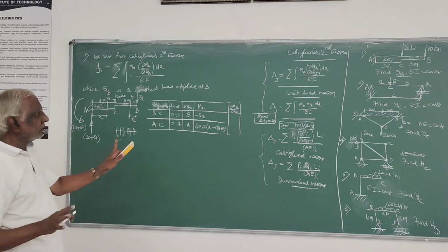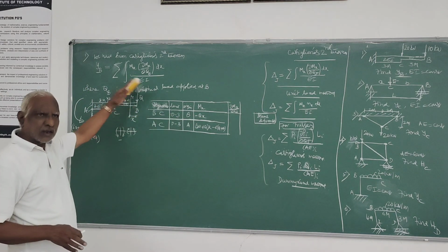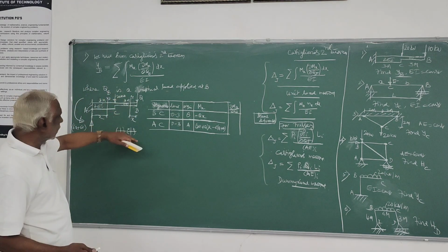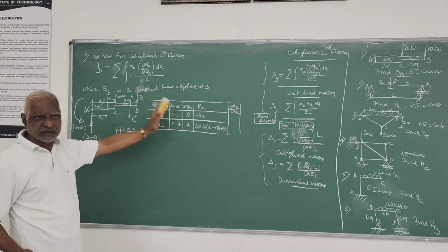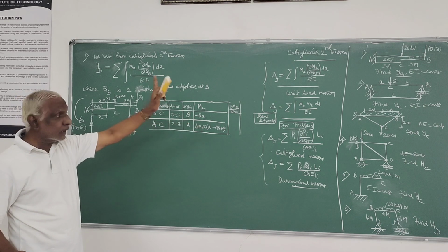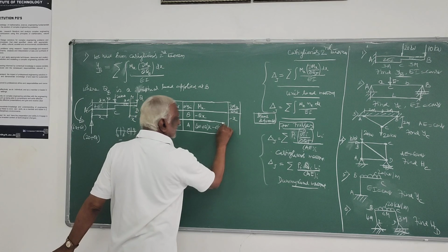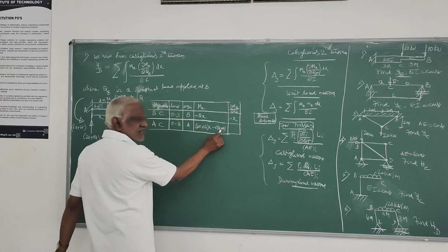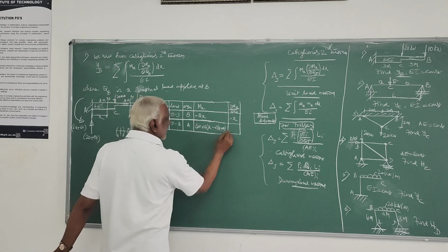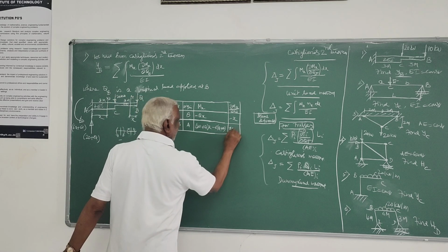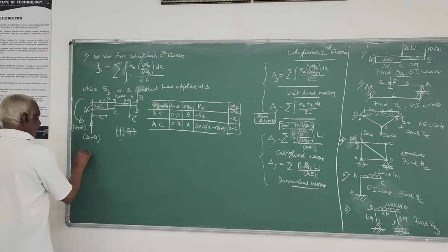It is just a problem of finding moment at different sections, similar to drawing the bending moment diagram. There also you take a number of sections, same kind of thing. Delta Mx by delta Q is the partial derivative. Here it is minus x. Here it is not 0, it is minus 6. Here it is x minus 6.